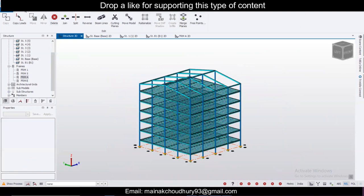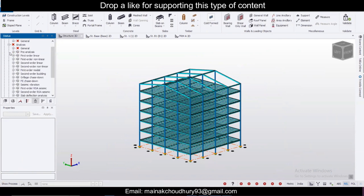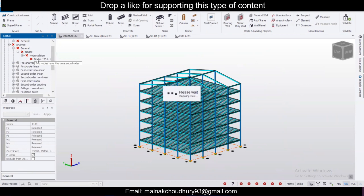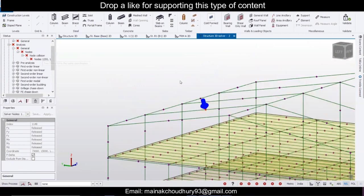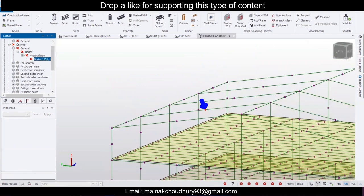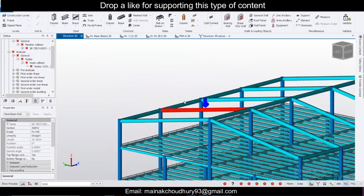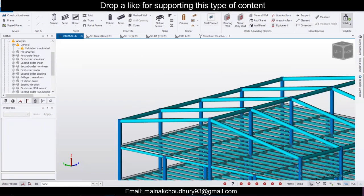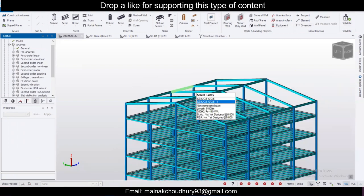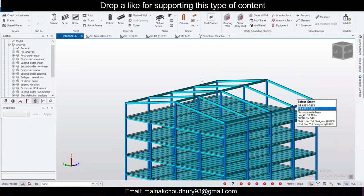So let's validate the model, just to check the model and validate. Yeah, we have some errors here. Node collision. Let's see where the nodes are collided. And member collision also is there. Okay, so member collision is there. So I'll just delete the member here. Okay, now let's validate. So it's okay. So I think I have placed the member twice here. So that's why the member collision. So that's an important check which you need to have.